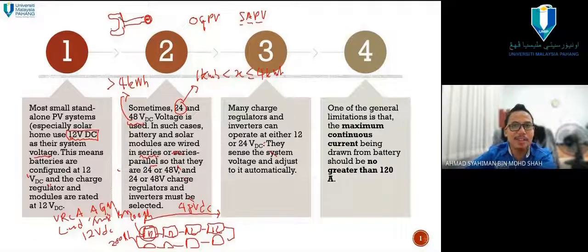When you try to open the bolt of the battery, please make sure you use gloves, made of insulating material. Maybe fabric is also okay, and rubber.